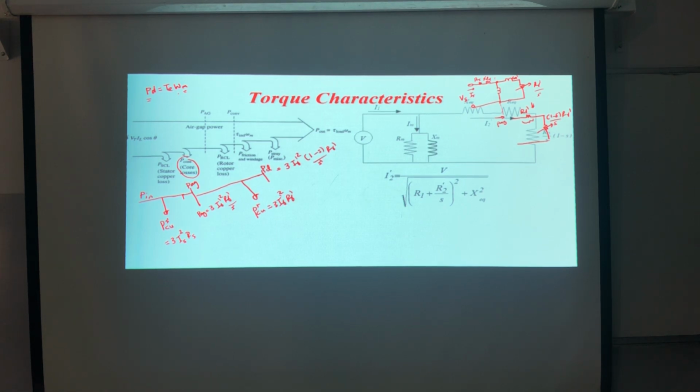Okay. So if I need to calculate the power developed, what do I need to calculate? I2 or what we call I_R dash, correct? Now how do we calculate the current? Simply, if I assume the simplification such that the delta Vs is equal to 0, which means that this branch can be moved here.